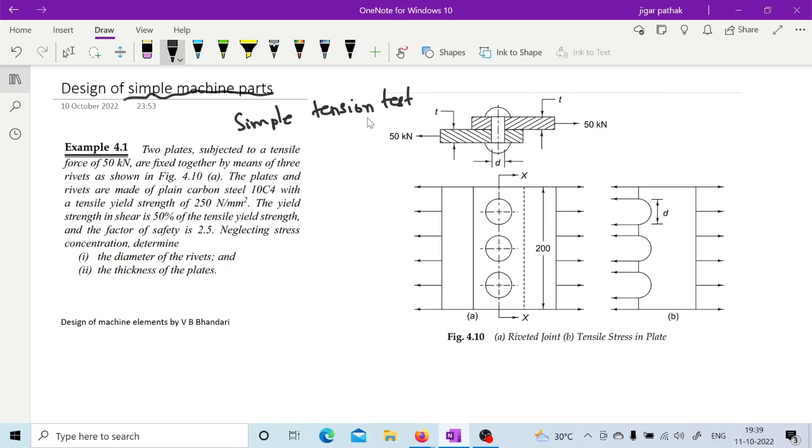You must have an idea about the material from which you are going to make that product, which strength it has, what the different magnitudes of all those strengths are, yield strength, fracture strength and all, right? And then you finally have to have an idea of which kind of failure theory you are going to apply. We will discuss the different types of theories of failure, but you also have to know which failure theory you are going to apply while designing your component.